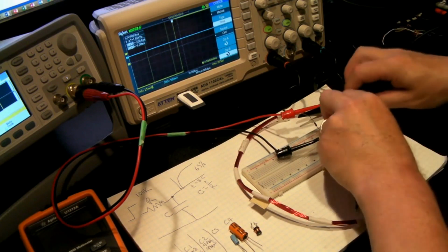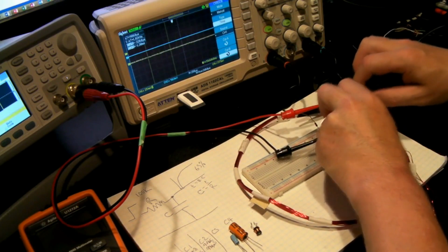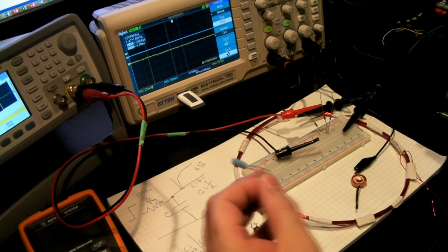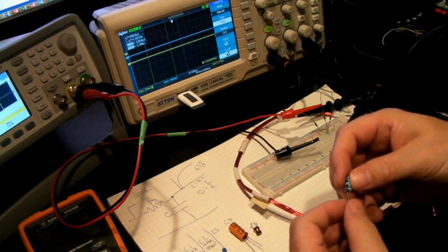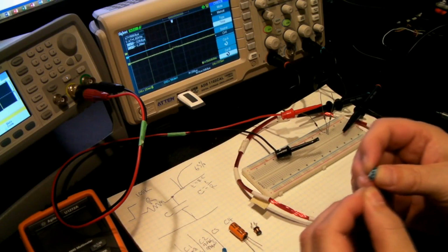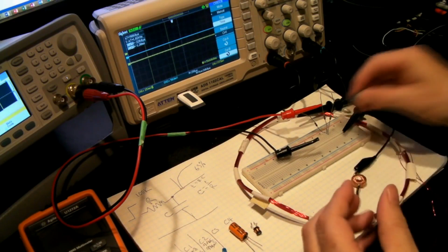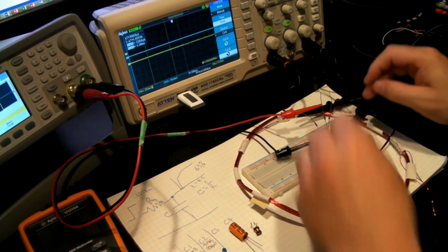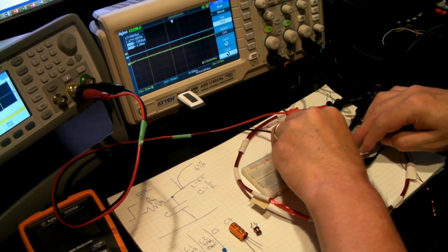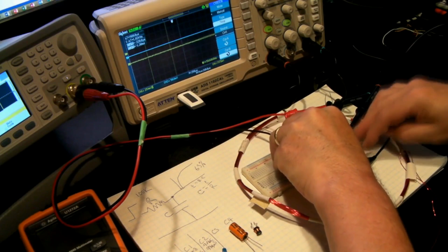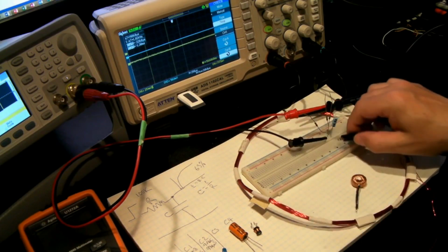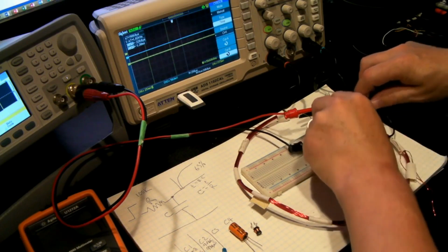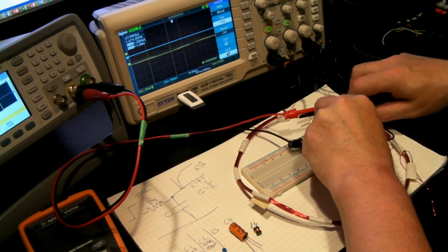And I'm going to pull this capacitor out now. That one here. Now the next one we're going to use is actually an electrolytic. But because we're using such a low voltage, it really isn't going to affect the electrolytic at all. So we should be able to just put this in, and because it's basically floating here as well, it's not really going to matter anything. I wouldn't do this with any high voltages on a capacitor like this, but this is just fine for what we're doing here. So I'm reconnecting that, putting the probe back on here.